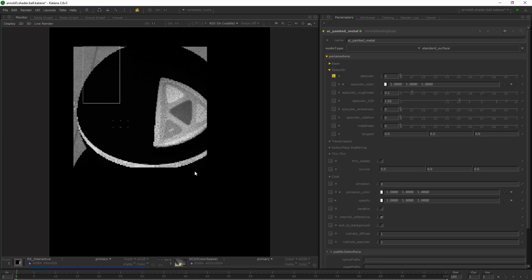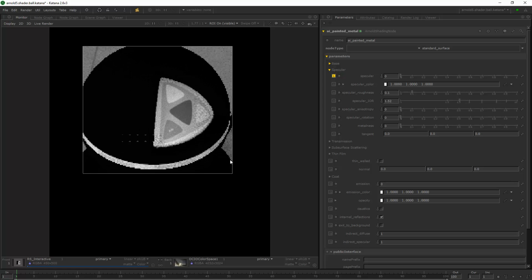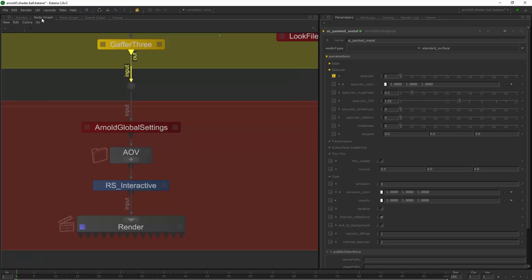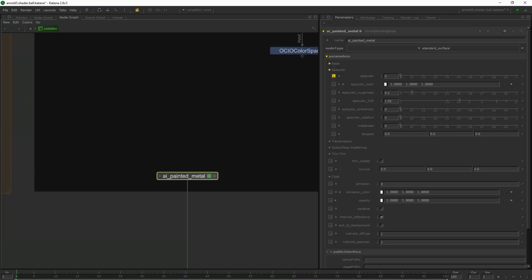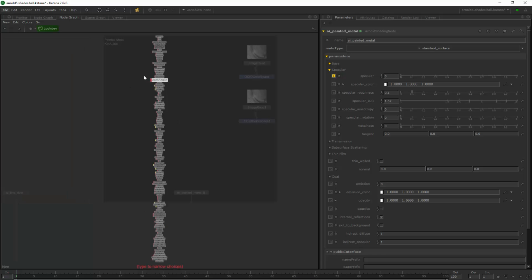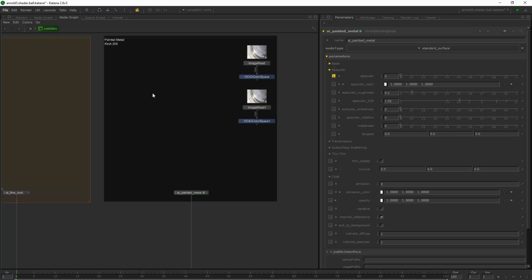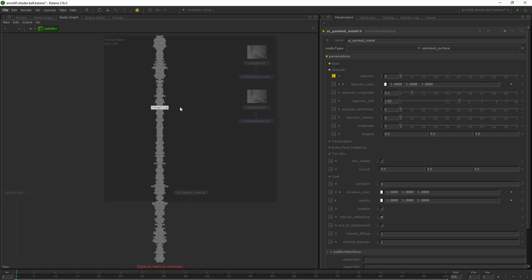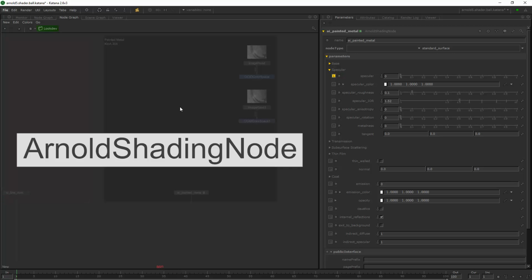Okay. And we might introduce just a few color alterations. I think that's the first thing we should do right now. So in my node graph, if I press Alt O, that's something I actually implemented, I get all my shaders in a drop-down menu. If you don't have that, what you need to do is create an ASN, Arnold shading node, like this.